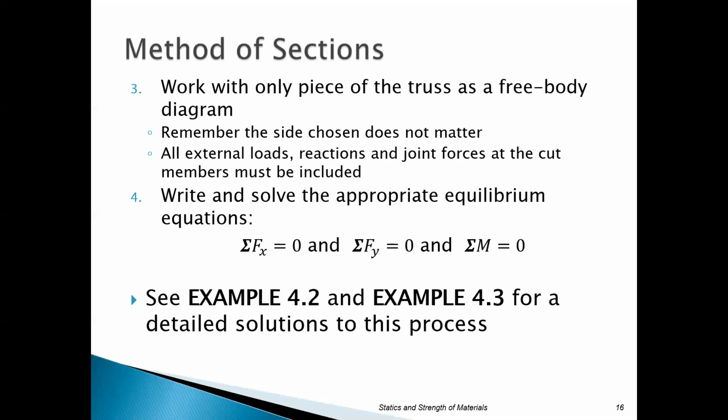Once you have completed that aspect, you're going to write and solve your appropriate equilibrium equations. So you'll have one equation of sum of forces in X equals zero, one equation for sum of forces in Y, and you can do multiple moments. So you have one X equation, one Y equation, but you can do moments at several different locations. And what I'm going to show you, I like to do moments in more than one spot, because sometimes that gives me a little check on my own math internally. But remember, it's not going to save me. If I've blown my reactions, I've blown everything. So I can't stress that enough.